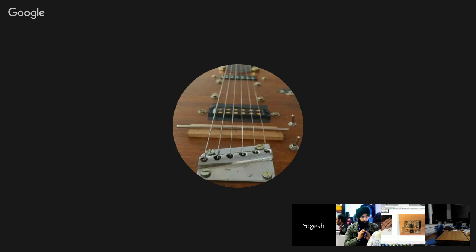And one more thing in the PCB: what is there inside between two tracks? That is the dust of the board which has filled up in the tracks, and I was unable to edge it out. It doesn't really make any difference to the connectivity, so I've let it be. But it is white colored dust, right? You have to clean it using water before stuffing the board. One more thing, you can use steel wool to clean it, and it will degrease the surface also. But degreasing with steel wool you have to do before milling, and after milling you can use any soft brush or toothbrush to remove that, and then wash the PCB.